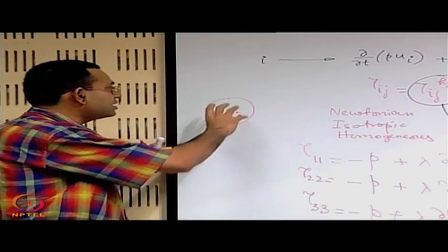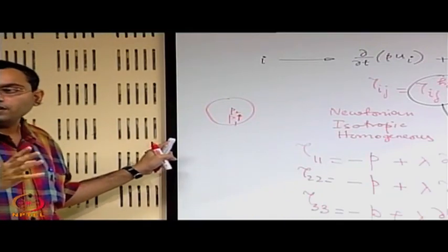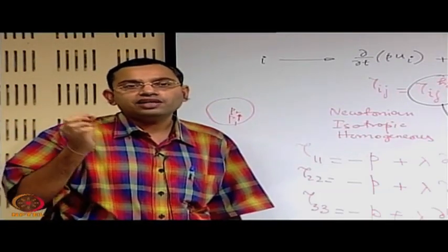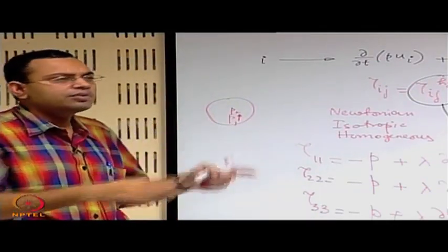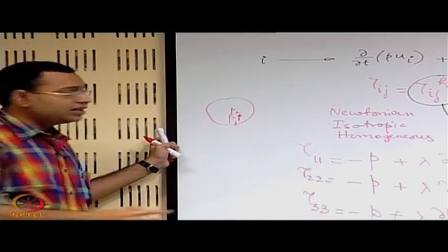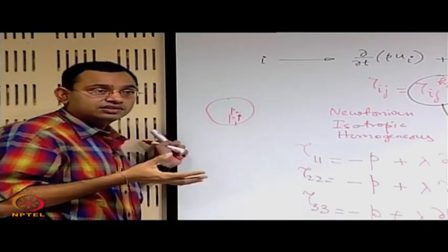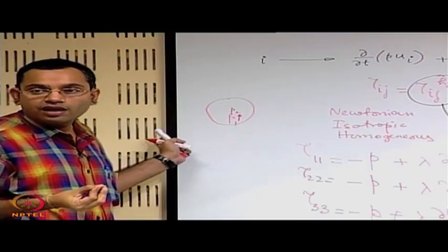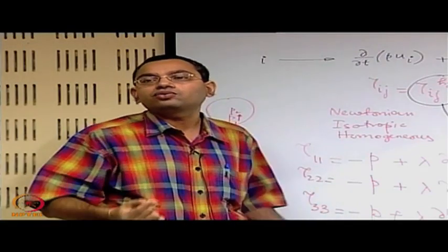Let us say that you have such a process in which a bubble is rapidly expanding and contracting. So if the bubble is rapidly expanding and contracting with a very high frequency, then that high frequency means it has a very short time scale over which the change is being imposed, and this change is externally imposed, maybe because of a change in thermal environment, maybe the temperature is fluctuating very fast or whatever, and the poor material inside the bubble is trying its best to adjust to that, but it is not possible to adjust if the change time scale is very rapid, and then it cannot equilibrate locally to come to a state where its mechanical pressure becomes equal to thermodynamic pressure.